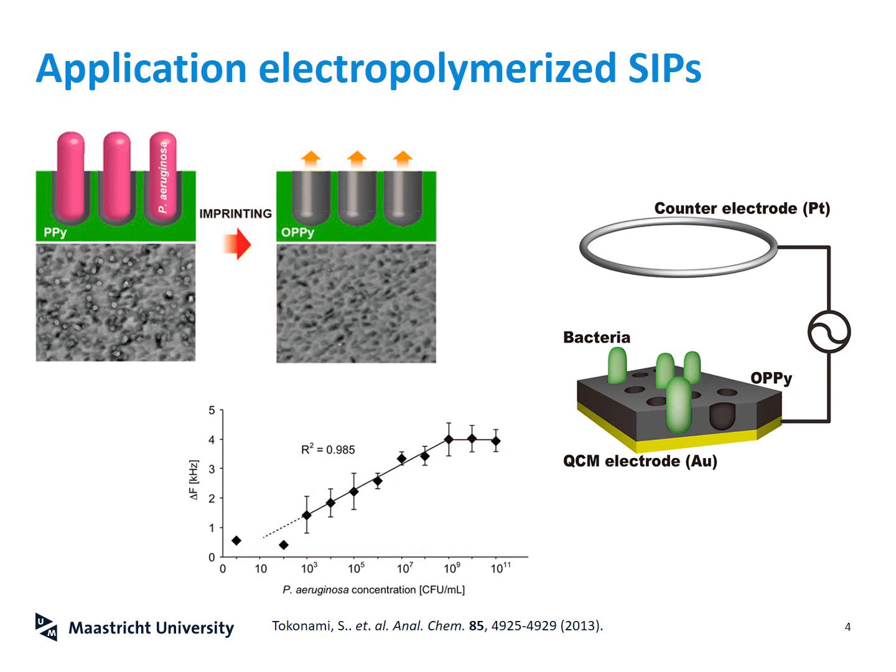Now, whenever bacteria, in this case, bind to the surface, the mass on the surface will increase. And of course, when something becomes heavier, at the same energy, it will take more energy for the crystal to shake, but you only have a limited amount of energy that you put into the crystal. So what happens is it will start resonating at a lower frequency. It will start vibrating slower. And as you can see in the graph on the top left side,